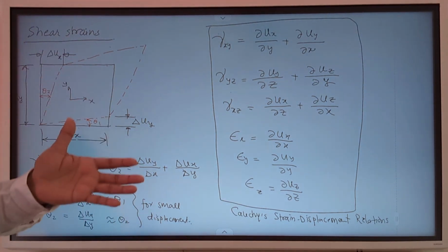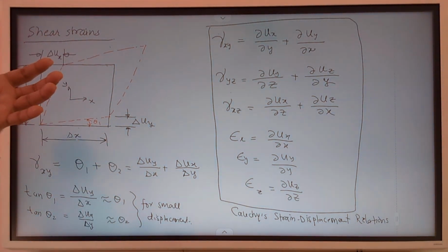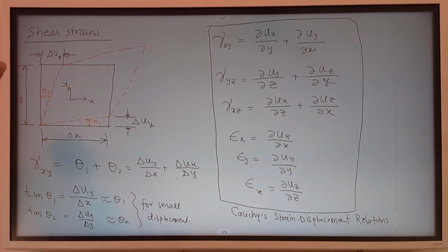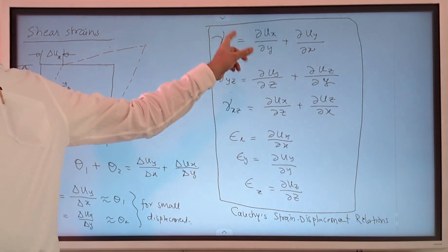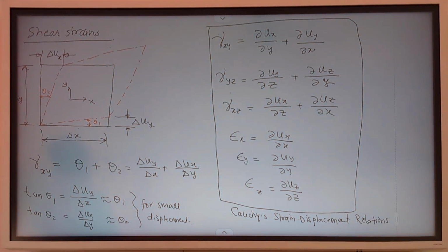That is how it gets used in the finite element method. First you obtain the displacement solution, and then from that you calculate strain using Cauchy's relations. And once you get the strain, use the relationship between stress and strain. That is what we are going to study next. But you are already aware the basic rule is Hooke's law. From strain you can calculate stress.